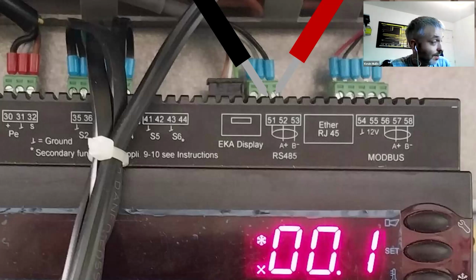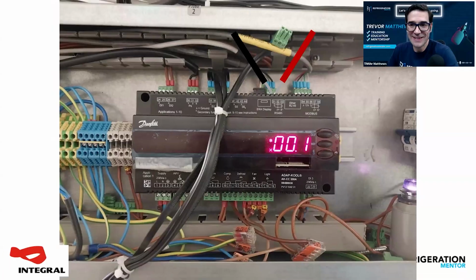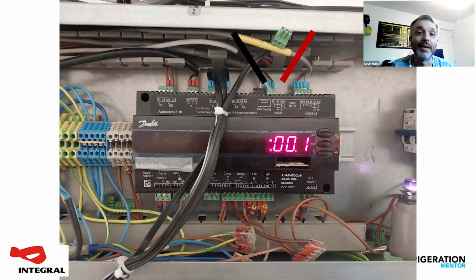It's worth checking. I would say with network fault finding, we could do hours and bore people to death on network fault finding. Yeah. Network fault finding is all about using logic. If you've got a whole island off, and the island next to it's on, the chances are your fault's on the cable between. If you've got one case on an island off, you can sort of break down where that fault is going to be.